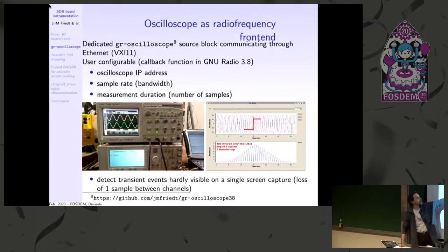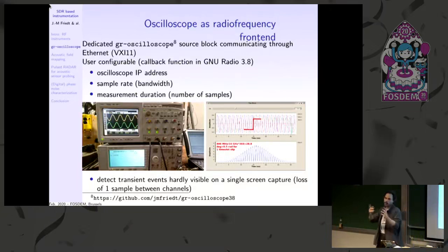You think that when you buy one of these high-grade oscilloscopes, if they claim that the 2 channels are synchronous, well, they must be synchronous, and this is absolutely not the case. If you look at the phase between these 2 channels, of course, this is an 800 megahertz signal fed to a 10 gigahertz oscilloscope, so we have about a ratio of 1 to 10 between sampling frequency and carrier frequency. Sometimes you see some of these jumps, so even someone as clever as Agilent has some missing packets or some missing data between their multiple channels.